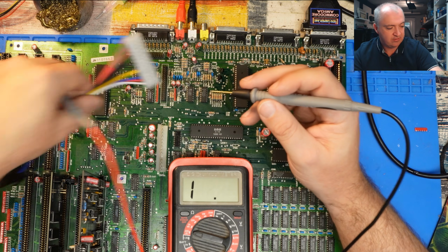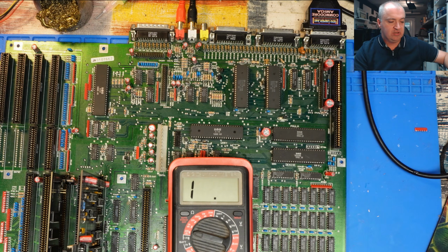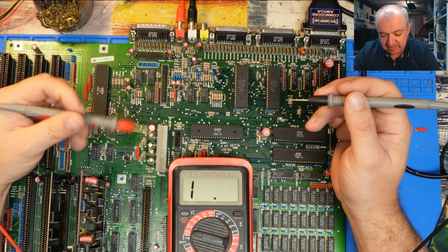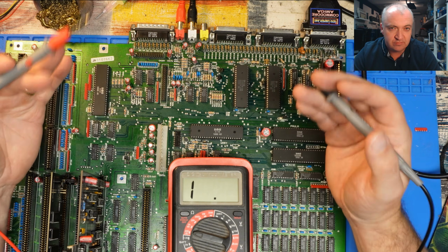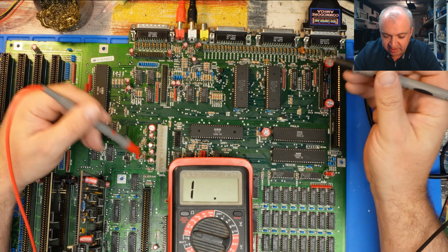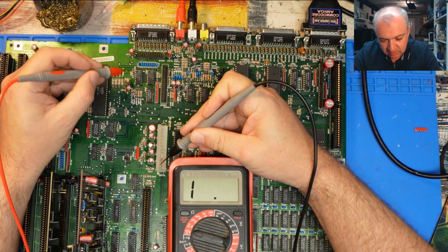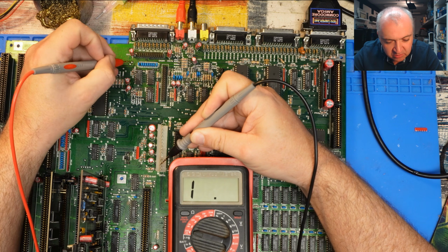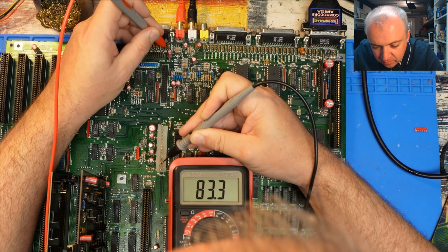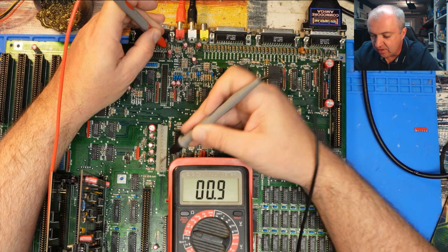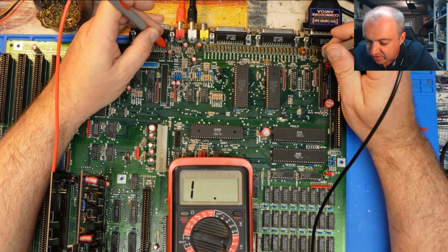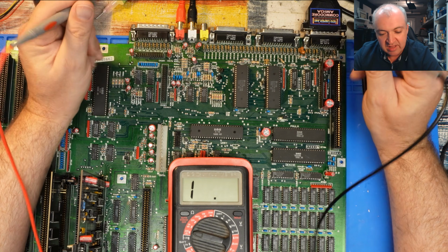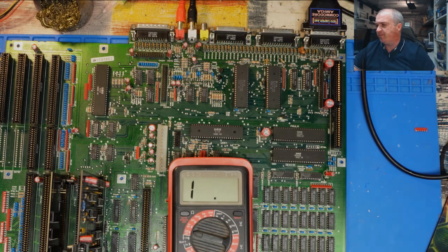But I think what might be going on here is that with the original A2000 PSU, that might be a dedicated video 5-volt rail, because that's certainly where it's headed. I mean, it's coming up here. It goes through here, up through one of these caps, comes out of the board up here somewhere, comes out of the board up there, and then makes its way down here. I think that's maybe supplying power to the hybrid. I'll need to pull up the schematics.